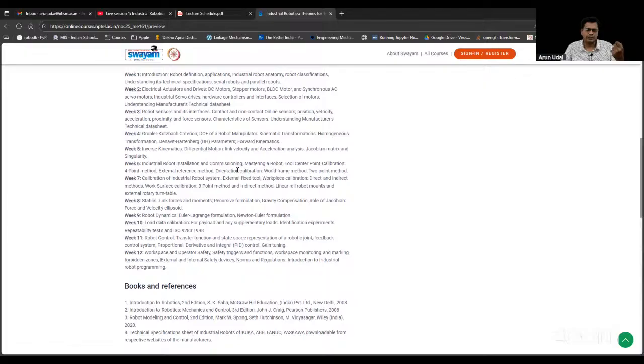The way I did forward kinematics, I started from the base center point to the tip of the robot, where forward kinematics normally should be done. In quite a lot of books, you may get confused because they don't cover it from the base of the robot; they cover it from the first intersecting axis to the wrist center point. That is not a good approach. So I would suggest you follow this. This is one of the best approaches, which an industrial robot controller normally also uses. And the same with inverse kinematics. I have used a similar way to do it.